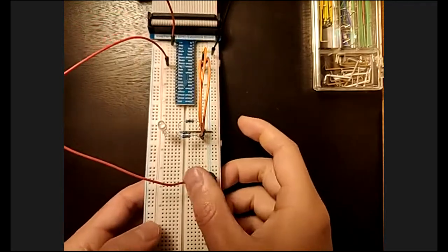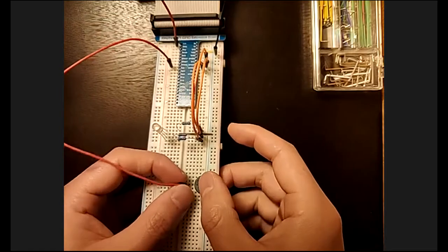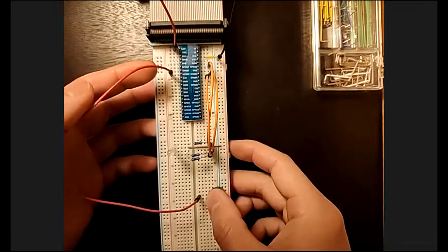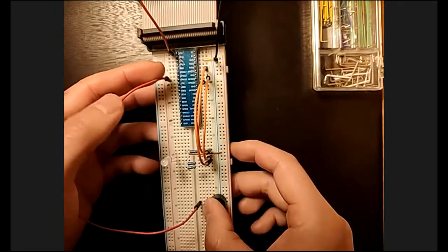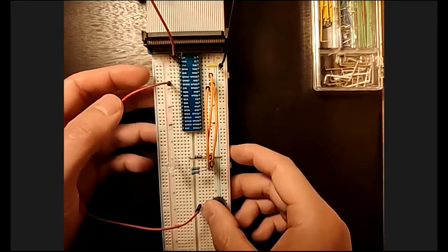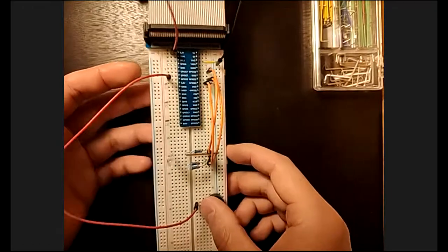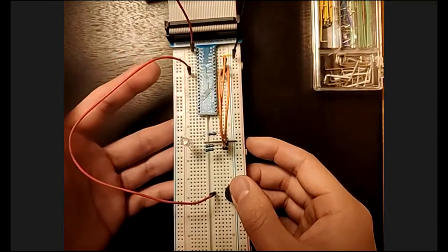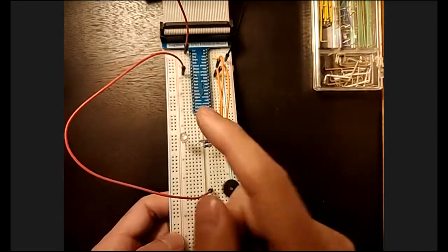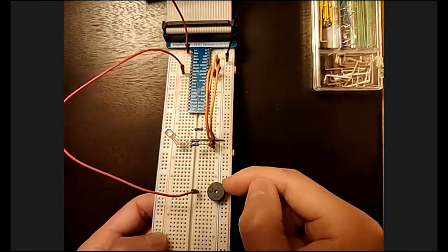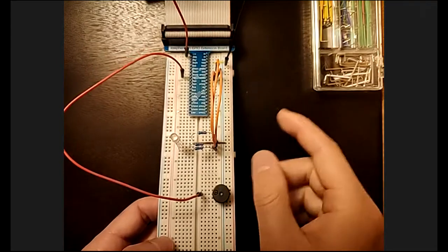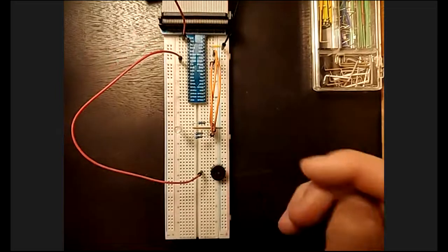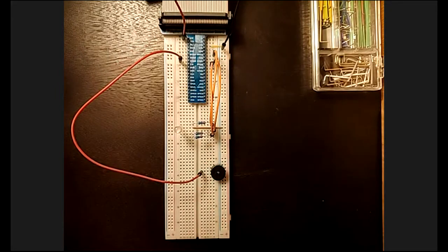And so I have this jumper wire here that connects back to one of the GPIO pins, okay? In this case, I chose GPIO 22. Now you can use any one of those. So this gives a 3.3 volt charge, and then the electricity flows through this buzzer and then back through the ground. And it's very straightforward. So you just connect that way, it'll make a sound. Now let's look at the program.